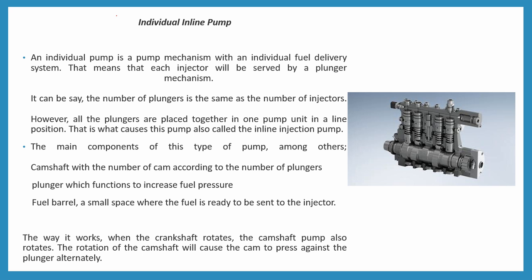So the way it works, when the crankshaft rotates, the camshaft pump also rotates. The rotation of the camshaft will cause the cam to press against the plunger alternately. So here is the picture of an individual inline pump.